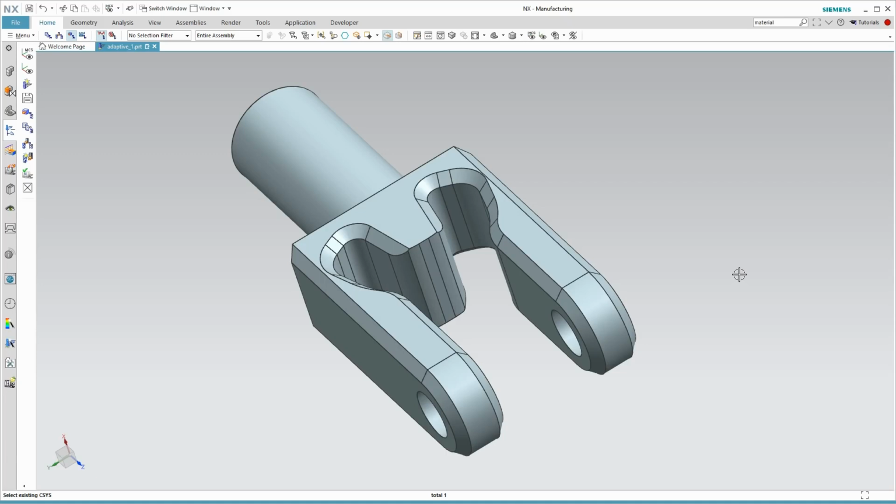I'm using NX version 1880, and this tutorial is specifically directed at our current users of NX-CAM who have in the past used the trochoidal milling strategy for roughing out their parts. Although trochoidal is available in cavity mill, I'm more interested today in the applications for trochoidal that were available in planar mill, and showing users how they can duplicate that same type of functionality using adaptive machining.